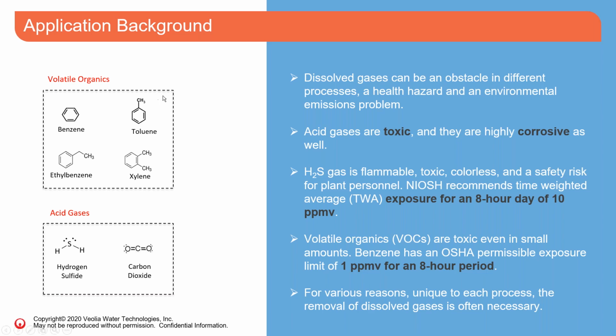The VOCs that you see here are commonly known as BTEX, which stands for benzene, toluene, ethylbenzene, and xylene. These, even in small amounts, can be detrimental to plant personnel. To put that in perspective, benzene has an OSHA permissible limit of 1 ppm for an 8-hour period.